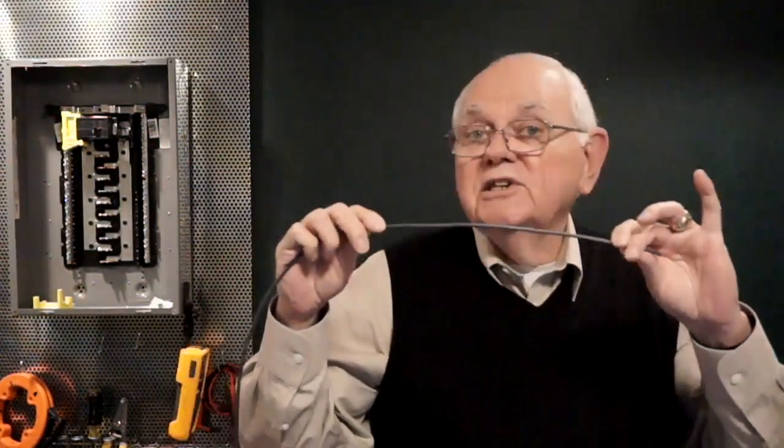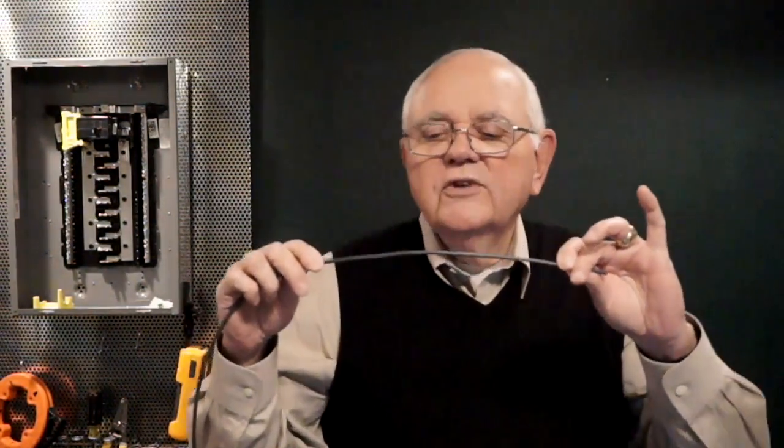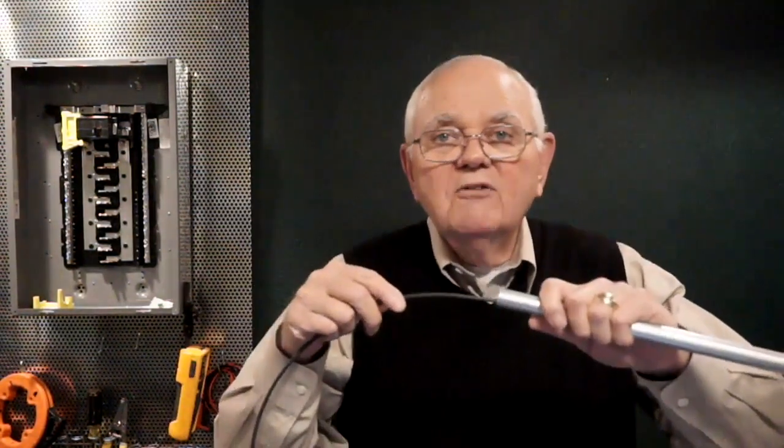So we just said that ampacity is the maximum current that this conductor can carry continuously, meaning under full load for 3 hours or more, under its conditions of use, and not exceed the operating temperature of the insulation. Now, what are those 3 conditions of use? We just talked about them. How many conductors do I put inside of my raceway? That's one condition of use. Where am I going to locate it? Dry, damp, or wet location. That's another condition of use. And then the third condition of use, what's the ambient temperature?